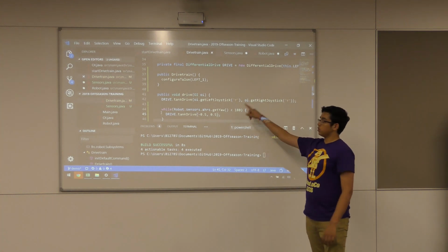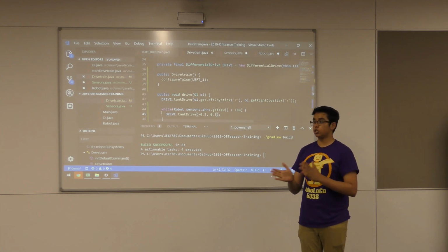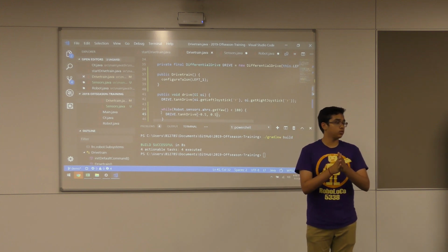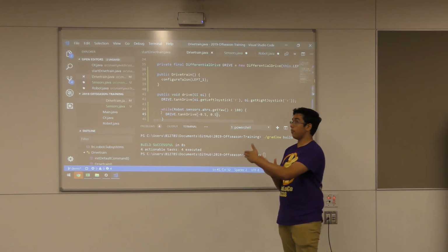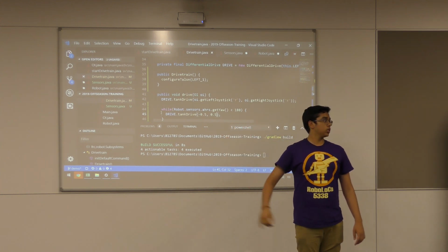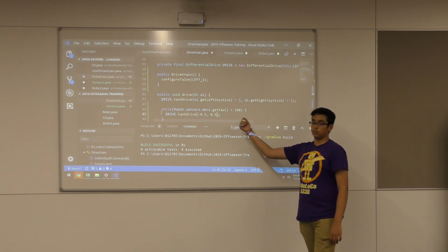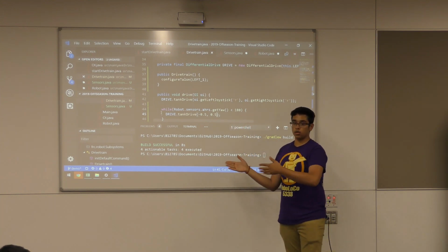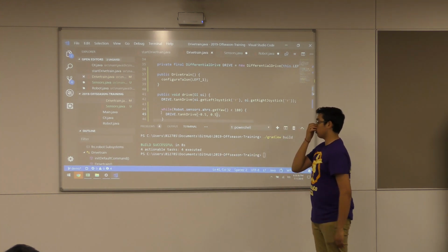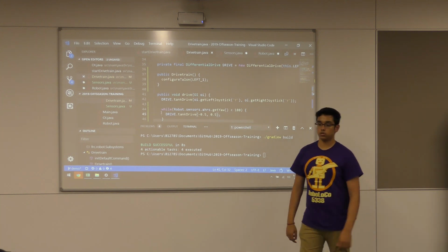And this is super ineffective because it overshoots, right? If you're just turning and the sensor says 180 and you stop the motors, what happens? The momentum carries over. Next time we're going to talk about algorithms you can use to make turning a lot more accurate. Although this will work to some degree, it'll skid because the momentum will cause it to overshoot. This is just a simple way that you can use the gyro sensor.